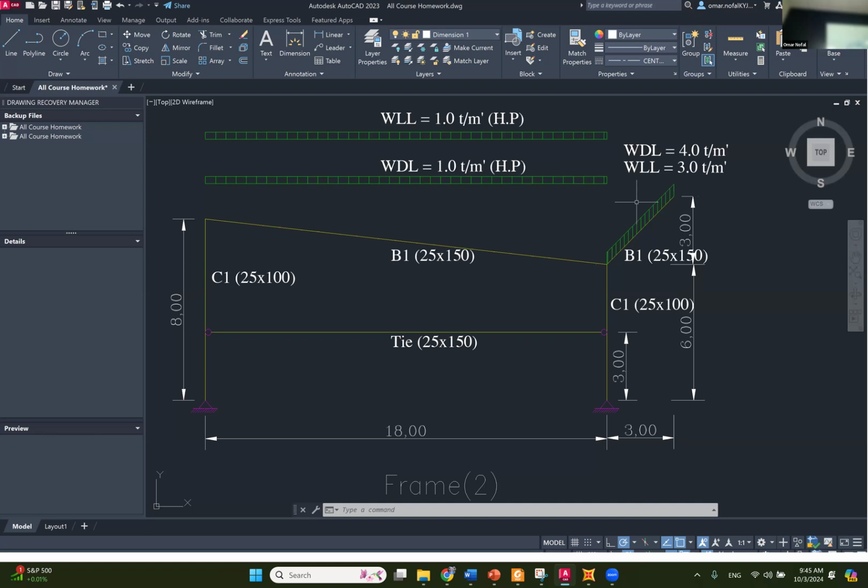We call it a truss member or a link member or a tie if it doesn't have any loads between the two hinges, and it has an intermediate hinge at first and an intermediate hinge at the end. So that means this member only has normal force, doesn't have bending moment, doesn't have shear force. That's from looking at this structure. Why? Because I have this intermediate hinge and intermediate hinge, so the moment is 0 and 0, and there's no load in between. But if you put load in the middle, this is not a tie anymore. It's gonna have bending moment.